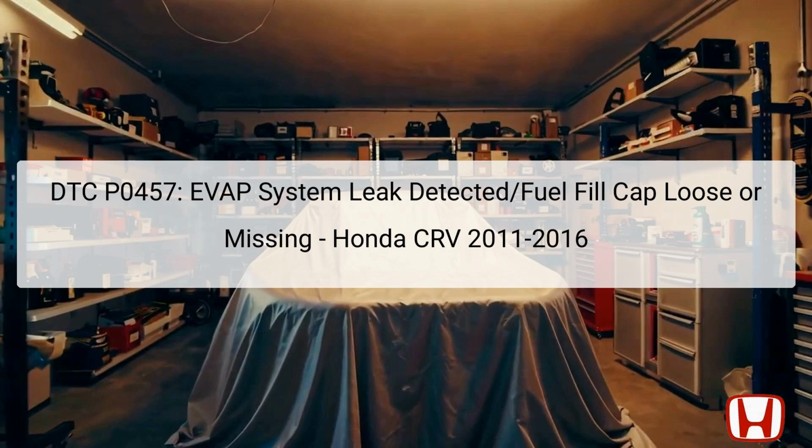This issue can not only lead to environmental pollution, but also indicate underlying problems in your vehicle, which might affect its performance. The fuel fill cap plays a crucial role as it seals the fuel system, ensuring no vapor escape while maintaining optimal pressure. If the cap isn't secured correctly or is damaged, it can trigger P0457. Before initiating troubleshooting, technicians should record all freeze data and onboard snapshots, providing a reference for any intermittent issues and the vehicle's operating conditions prior to the DTC appearing.